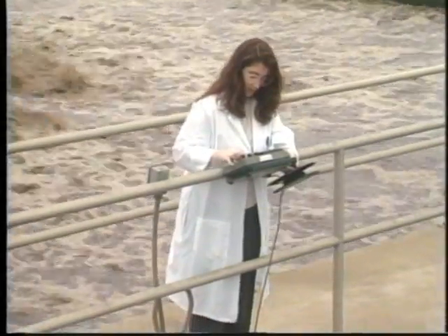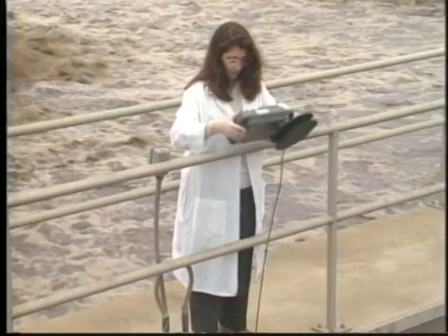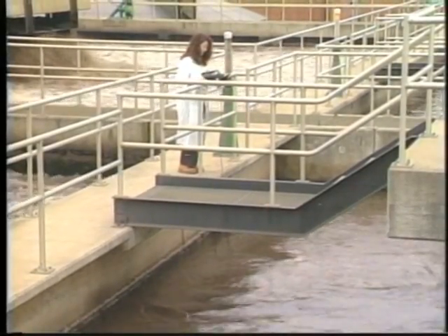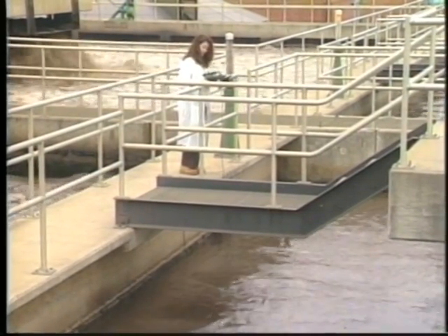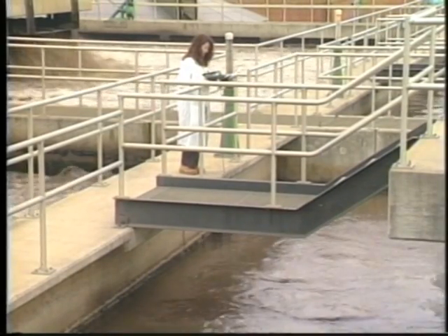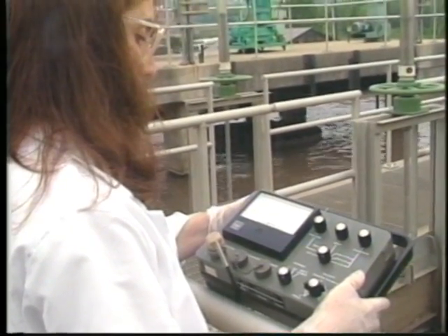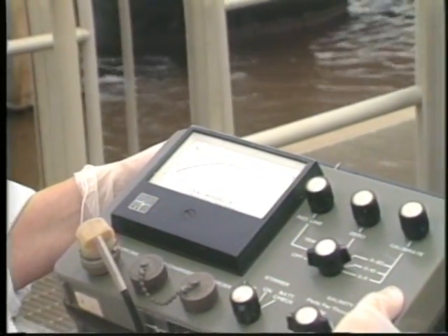One of the most important tests in an activated sludge treatment facility is the dissolved oxygen test. When checking DO levels, you should do a profile of the entire aeration tank. Generally, it is good to maintain a dissolved oxygen concentration of 2.0 milligrams per liter throughout the aeration tank. Low DO levels can lead to the formation of filamentous bacteria that cause the sludge to settle poorly. If the DO becomes depleted in the aeration tank, the contents of the aeration tank will become septic.